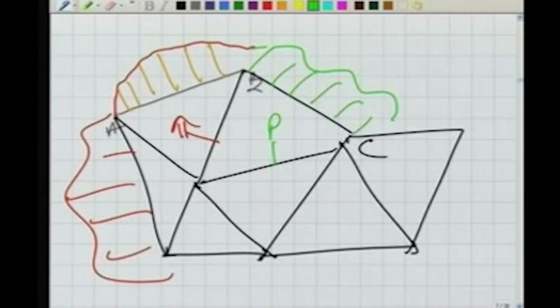So what we are seeing here, again, is the concept of working from whole to part. For our entire area, we did not start taking measurements from a single offset, a single detail. Rather, we started taking the observations in a big way. First, we made a network of triangles. So this network of triangles is the skeleton of the area. The skeleton of the area is captured. Then in our drawing sheet, we can plot this skeleton of the area. This set of triangles is done very accurately.